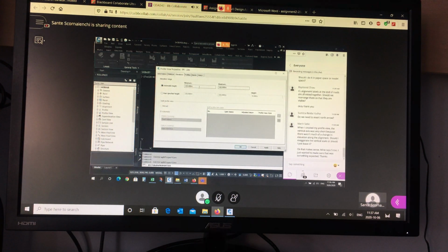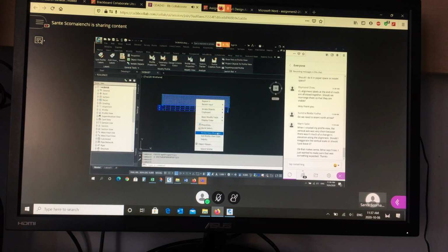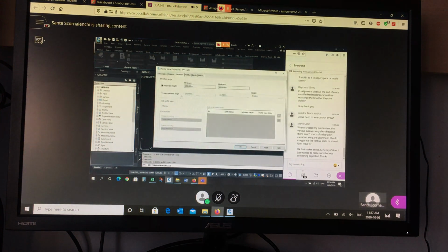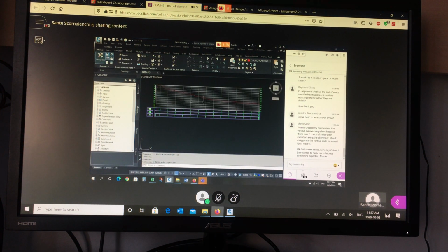Okay? Later, we will change this. I can make this as high as I want. I can go to 170, and it makes my grid higher, but there's nothing to show there. What we will do later, if required, when we go to the properties, we might add to the bottom. We might actually make this lower. I might make this 1 or 2 meters lower. Let me do 3 meters lower. I might add to the bottom because I want to see pipes underground.